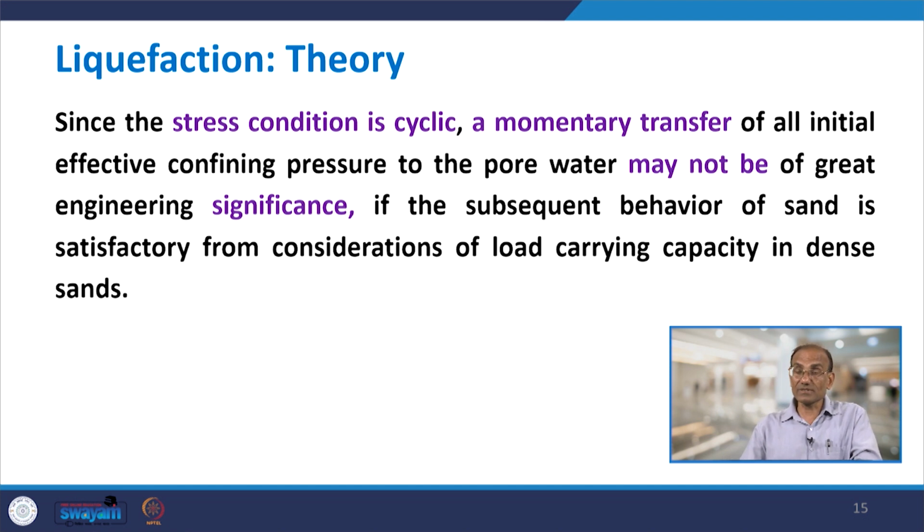Due to the cyclic nature of the loading, a momentary transfer of all the initial effective confining pressure to the pore water may not be of great significance if the subsequent behavior of the sand is satisfactory from consideration of load carrying capacity in dense sands.